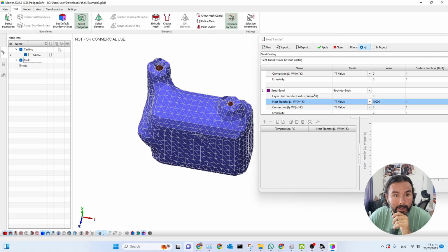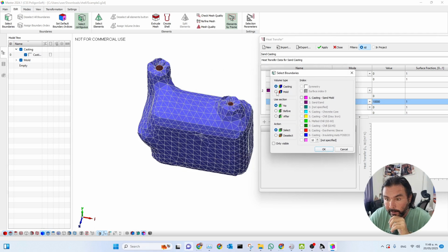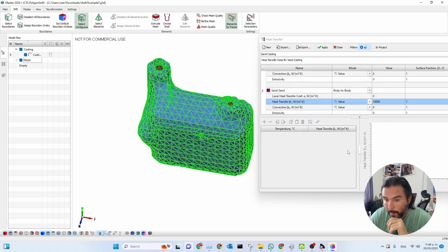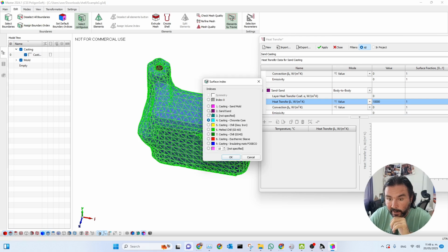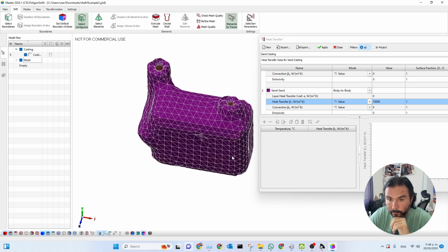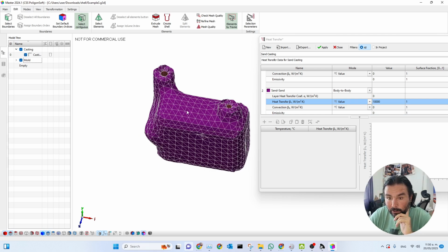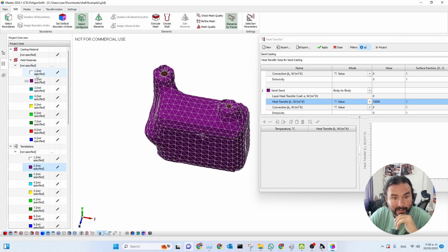We now need to go to the Edit tab, select all indices in the mold that correspond to index 18, and assign them the index we created, which is 2. Now, as we saw in the previous class, the one where we made the virtual mold, if there's no material outside the index, for index 2, the material, it will look in the material list for the one corresponding to 2.